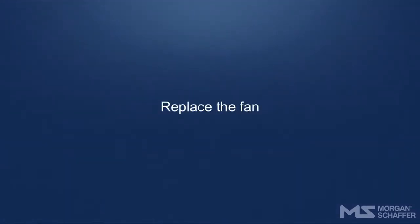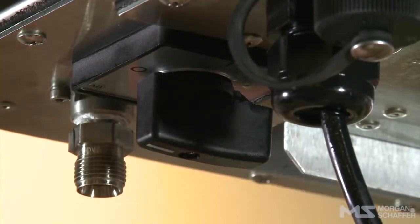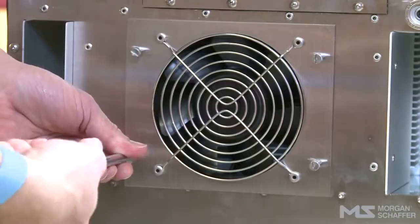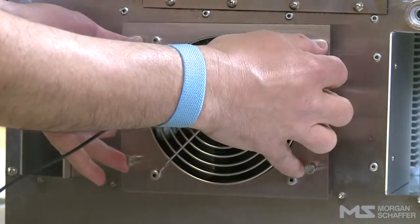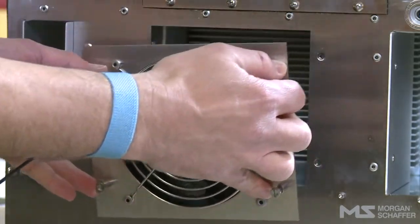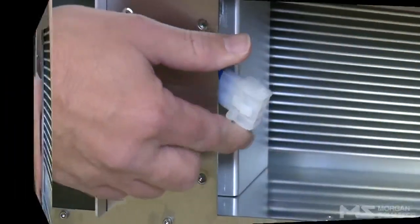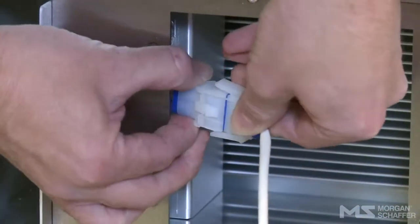Replace the fan. Turn off the Calisto and close its circuit breaker. Loosen the fan's 4 captive screws. If necessary, use a flat screwdriver to release the fan from the Calisto. Unplug the Calisto fan's connector. Set aside the old fan and prepare the new one.